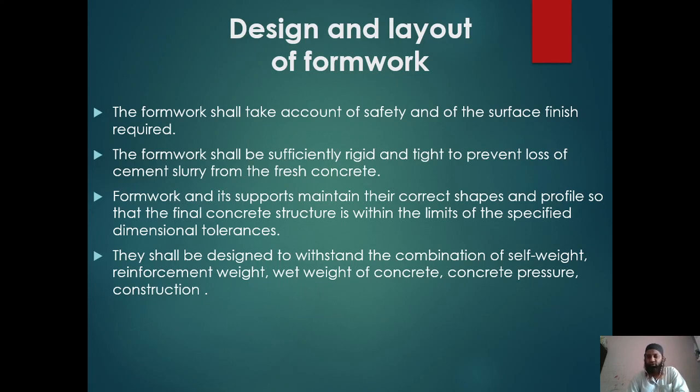They shall be designed to withstand the combination of self weight, reinforcement weight, wet weight of concrete, and concrete pressure. As I told you, there is not only pressure of concrete, but reinforcement weight is also there. Live load is also there, where people keep on moving onto the slab. So all this should be taken by the specified formwork.